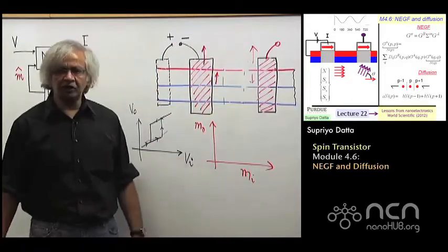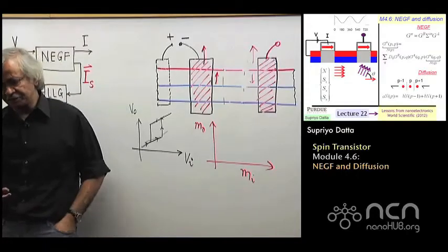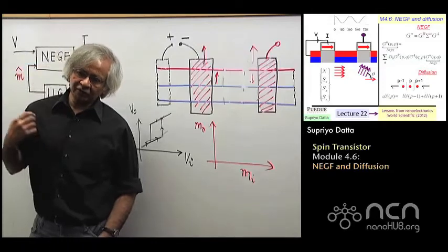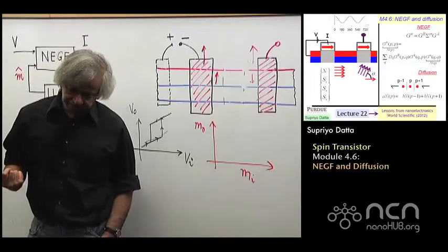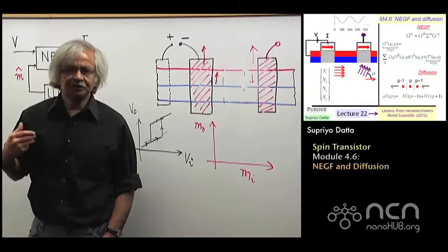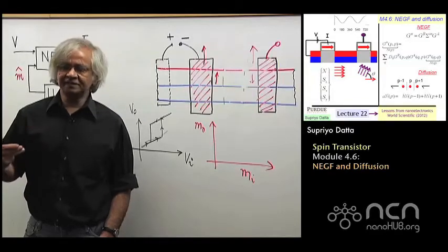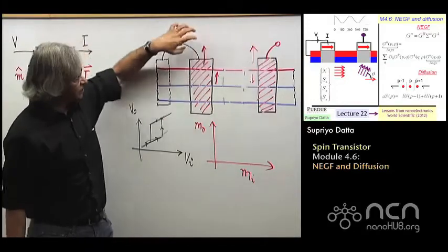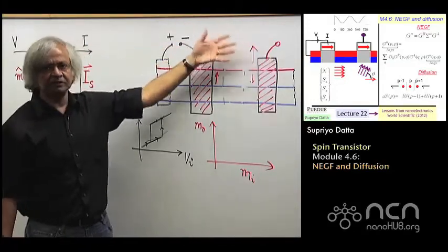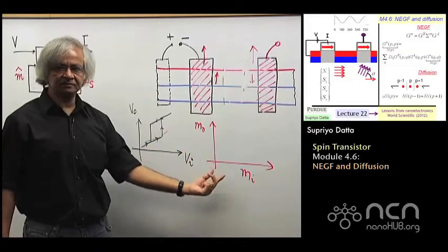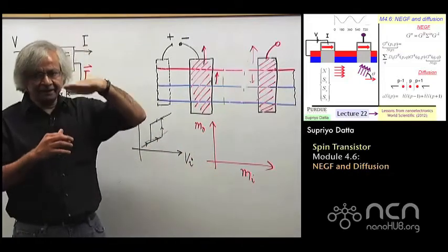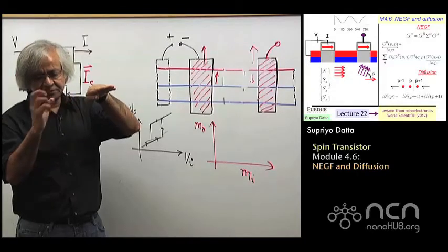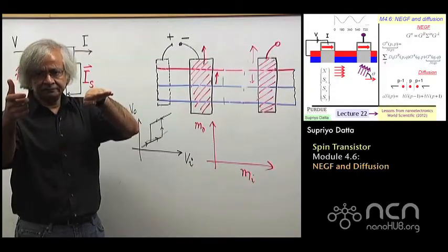So that is part of the thoughts that people have in this area now, that maybe in order to have a spin transistor, you should start thinking of systems where even the external information is not in the form of voltages, but in the form of magnetizations. So that you have magnets that contain the information, they inject spins, and these spins go and turn another magnet.